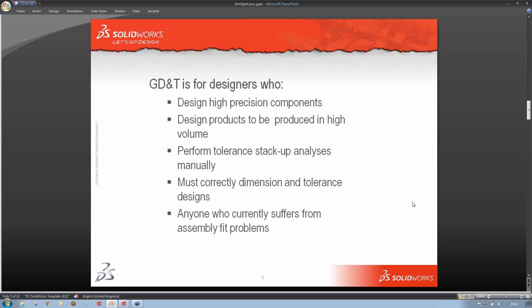It also allows us to perform a tolerance stack-up analysis, and that is something that's actually built into SolidWorks. The Tolerance Analyst tool, you can add it in, and you can use all of the tolerances that you've placed on all of your parts in an assembly to stack up the tolerances and actually get the variation of one particular dimension based on the tolerances of all the other components, which is a really handy tool, and perhaps we might come back to that in another webinar or something.